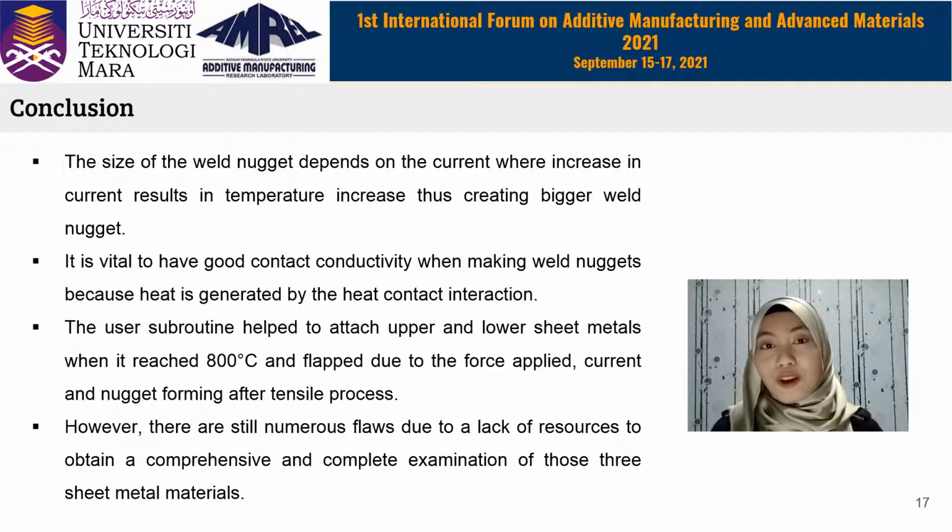Furthermore, the use of a subroutine in this modeling process aids with the attachment of the sheet metal once it reaches 800 degrees Celsius. Above all, after allocating data input to the resistance spot welding process, this simulation simply explores the physical condition of those three sheet metal materials. However, there are still numerous flaws in the study due to a lack of resources to obtain a comprehensive and complete examination of those three sheet metal materials.